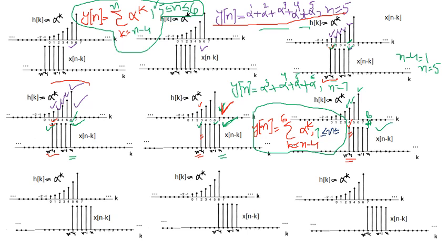So now you see n coincides with 8, so we have the expression where the upper limit of the summation is 6. Why? Because although this signal is crossing 6, it is non-zero and this signal is 0 beyond 6, so the product will result in 0. So we have the upper limit as 6.